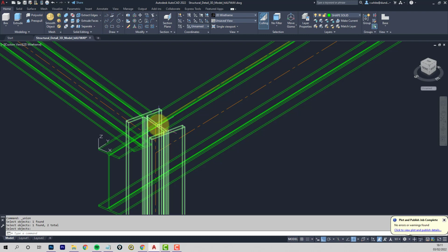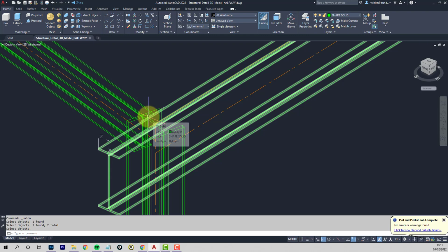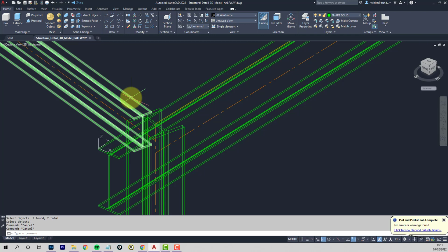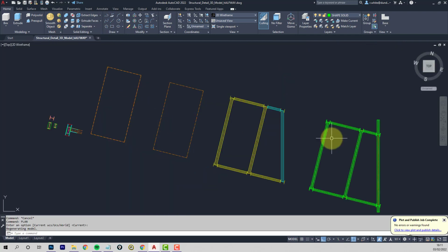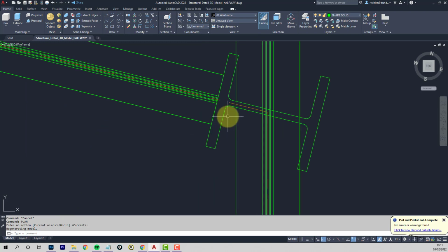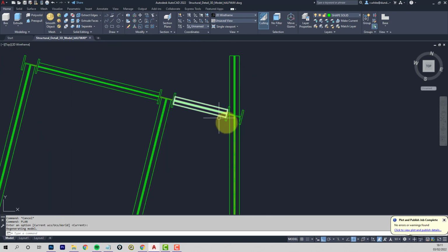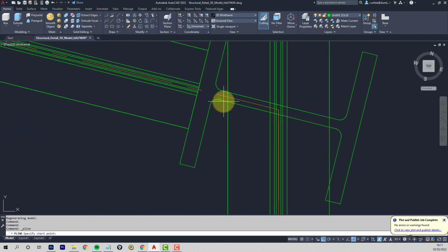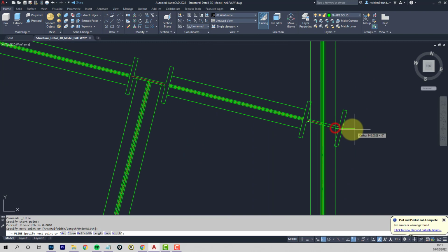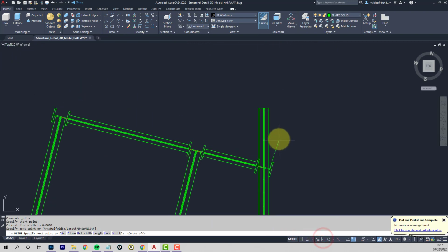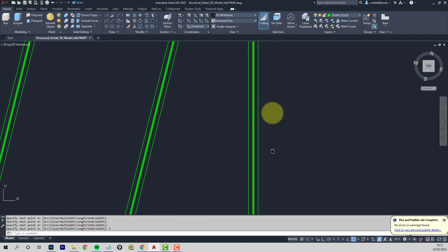Now what we want to do though is our subtraction. So this is a bit cruder. Let's view it from the top, and we want to create a shape that's big enough to chop that end off. So it's a polyline, not a spline. Use a polyline. I'm going to go from here to here and then switch ortho off, and I just need to go around the end of the object and close the shape. Do the same at the other end.